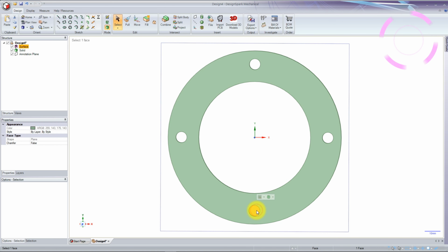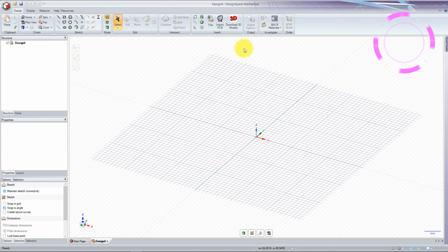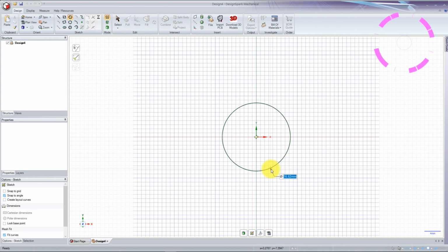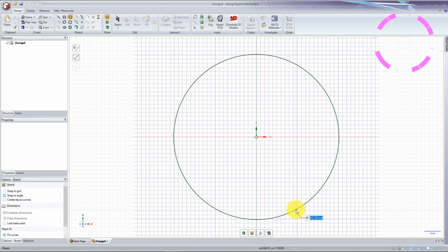In DesignSpark, which by the way is free, I will put the link in the description, we work with sketches. And here I want a top-down view on the Z-axis, so I go down here and I just click, and this will now represent our print bed. So, sketches, and this one is quite easy because it's based on circles, and the outer diameter of our gasket will be 110 millimeters. There we are. It just made me set a home view, so if I get out here, it will be easier to come back to normal.